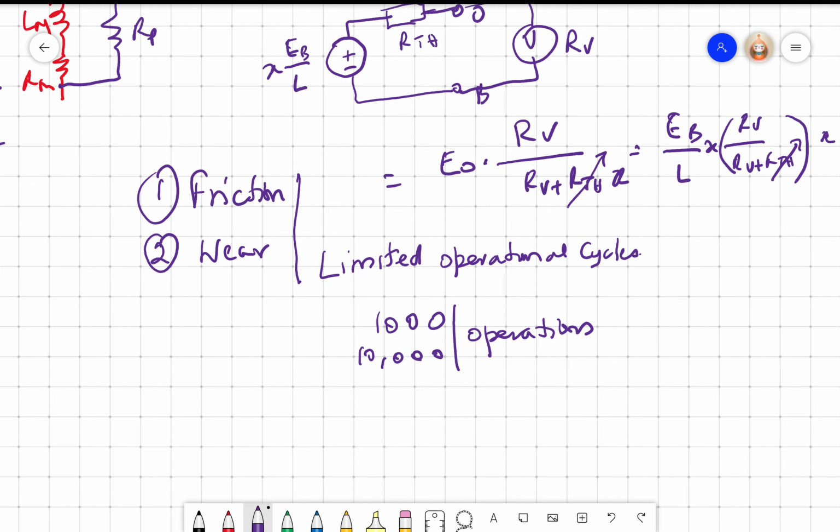One place where it is used is the automobiles. You have what is known as a brake, and the brake actually wears out because every time you apply a brake, it gets degraded. And there is a very small sensor called a brake wear sensor. It simply informs how much of the brake shoe is left, and that's a simple resistive displacement sensor, right?